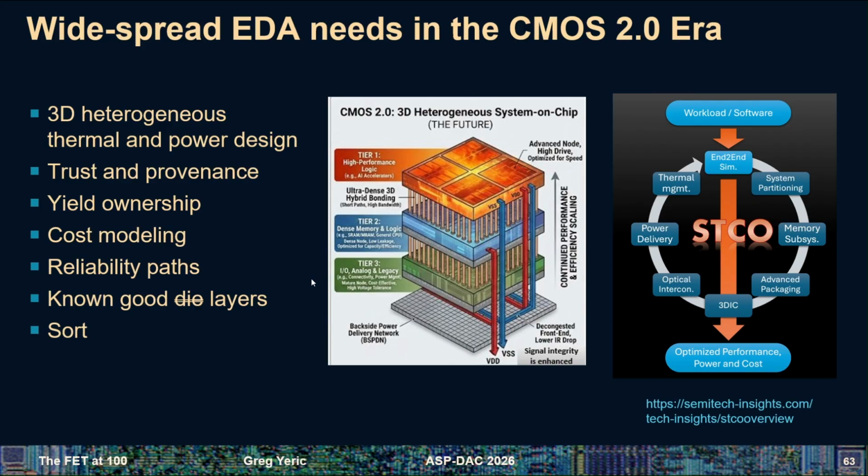The way that, say, Intel works is that, due to statistical variation, primarily gate length variation, the chips that come out with shorter gate lengths, but within the expected range, are going to be faster. And the chips that come out with longer gate lengths are going to be slower. So what Intel does is they sort the die through testing. The fastest ones get sold for the most money, and the slowest ones get sold for less money. In this case, what I mean by sort is, you're assuming that a chip is going to be in spec, but once you have multiple layers with multiple specs moving around, it becomes a little more complicated. So that's what I meant by that.